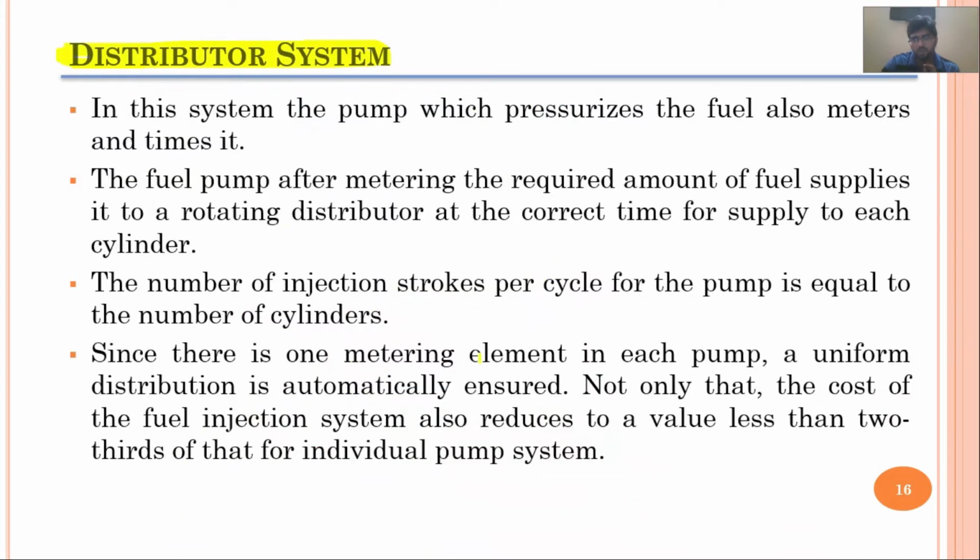And they are most commonly being used because they have multiple advantages. The first one is that uniform distribution is ensured in each cylinder, and they are very less costly as well, since there is only one pump being used, and they are also very easy to maintain, because there is only one pump which is pressurizing the fuel.